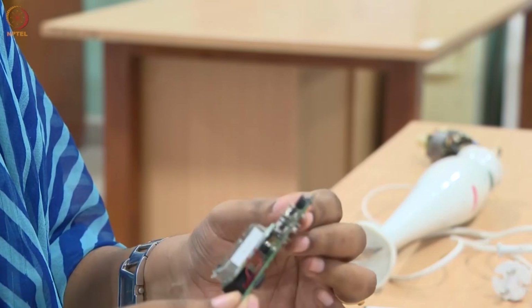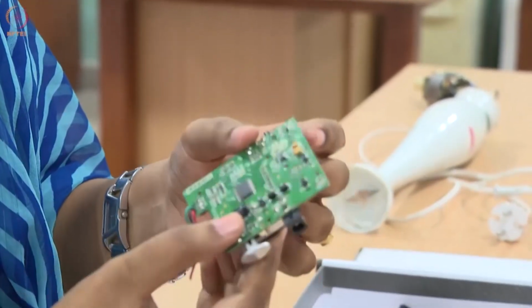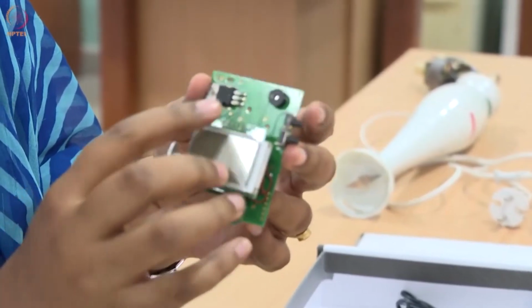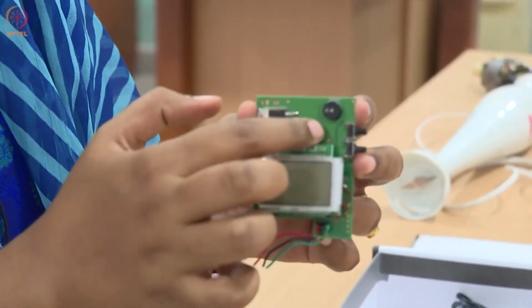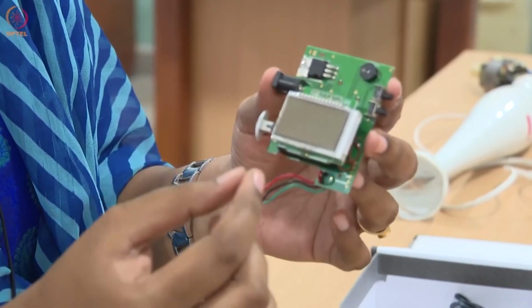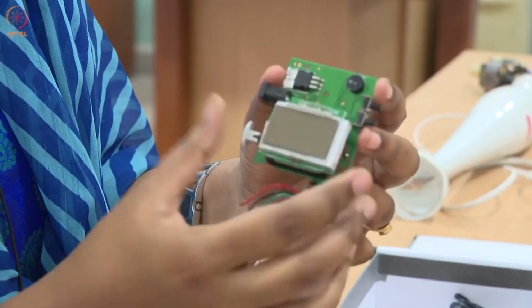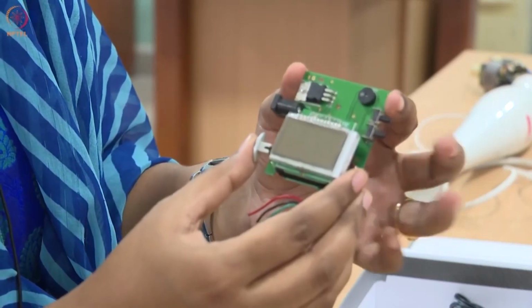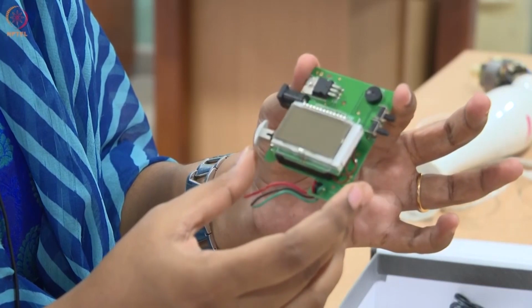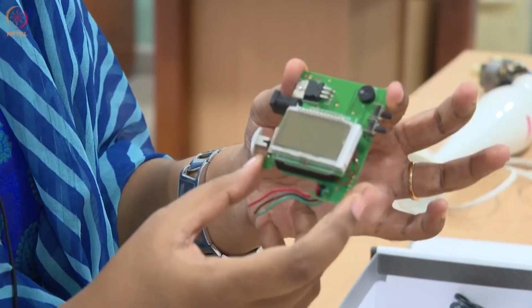Here they have just gone for a dual layer wherein you can see on both the sides there are wiring and wire points. These holes are drilled using special drilling machines, and they will be again coated with the oxide layer and copper layer. Copper layer first and then oxide, and then finally lamination and several other processes of giving out the PCB board.